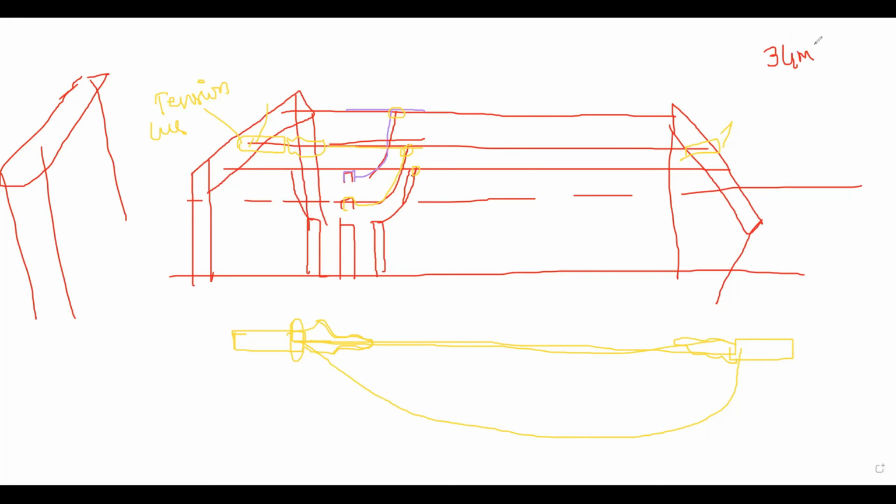So after that, I am having one more bus. This bus is connected again by having tension insulators, which we discussed. But this is totally the same bus, so I should connect this bus to this bus. I am connecting like this. For this support, I am placing an insulator from the bottom. This insulator and associated hardware, we will call a suspension insulator hardware.